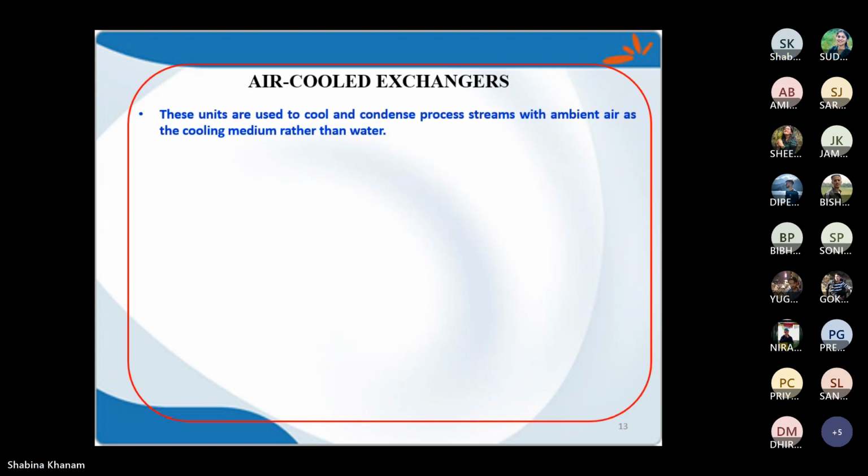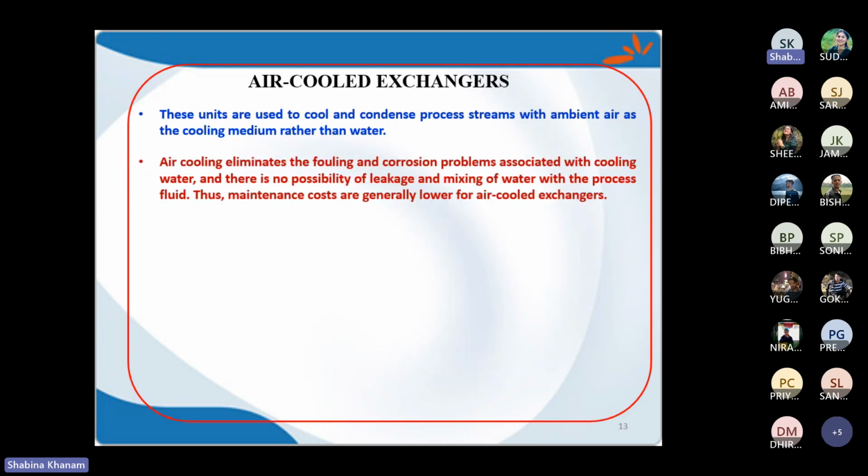Because air does not have the fouling tendency, this air cooling eliminates the fouling and corrosion problems associated with cooling water, and there is no possibility of leakage and mixing of water with the process fluid.